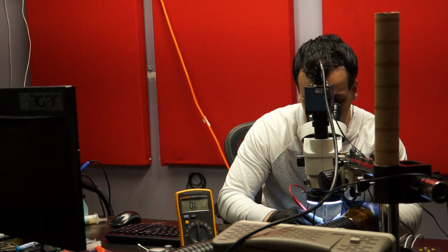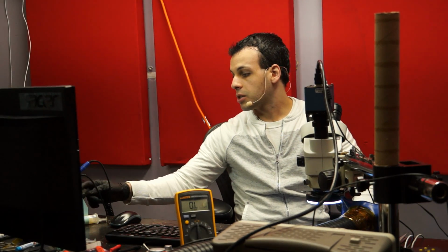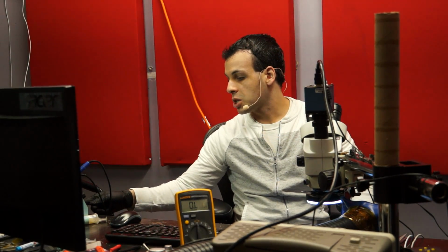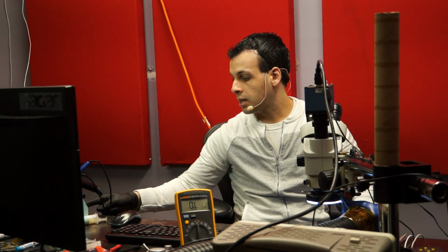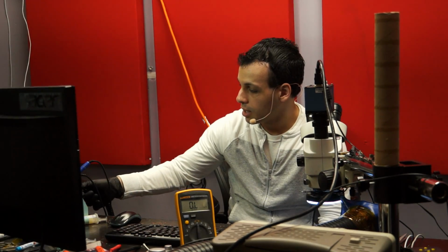So let's measure resistance on that, and I'm pretty sure the signal is being pulled down because that chip is intermittently failing. It's 49.4 kiloohms, which is below 100 kiloohms, which means my U7200 is what's screwing all this up. So I'm going to turn on my Weller WHA900. I'm going to take a break, make myself some breakfast or lunch, and come back in a half hour. Hopefully this thing will have heated up by then.